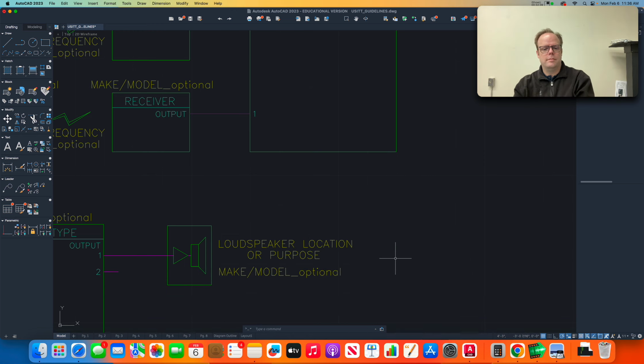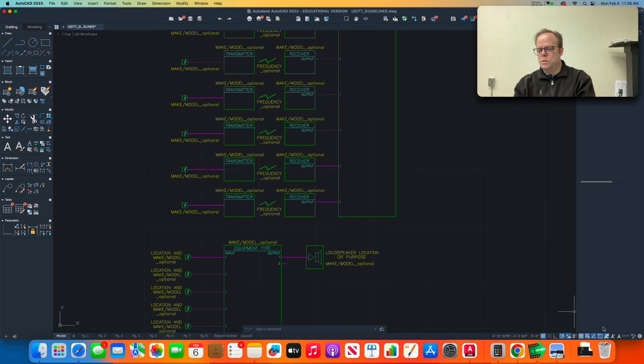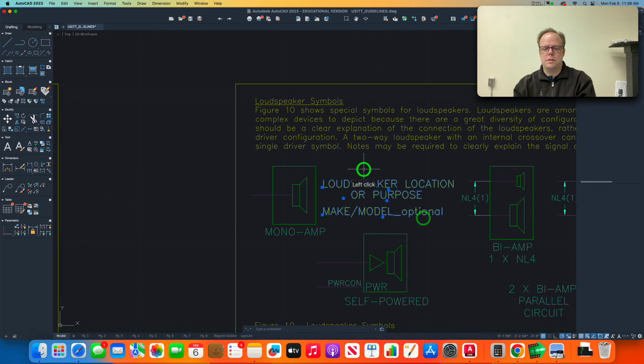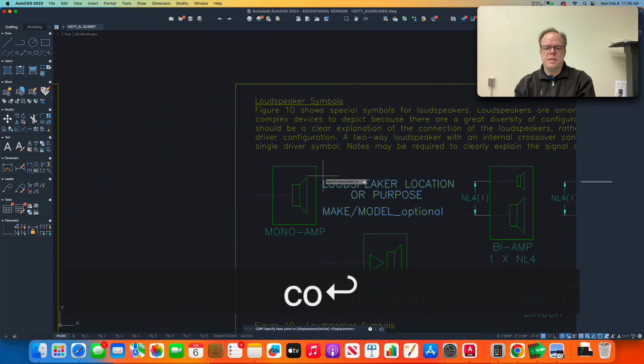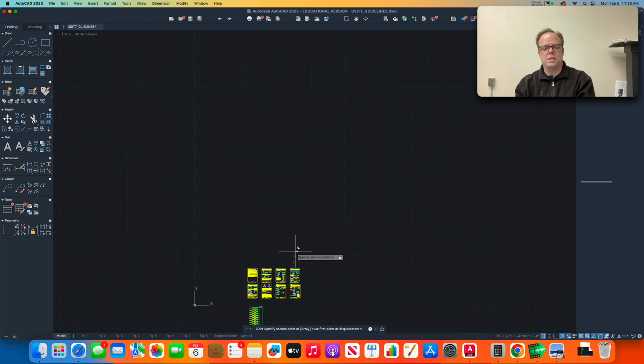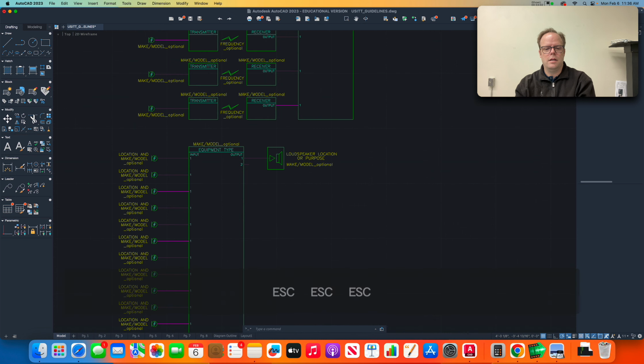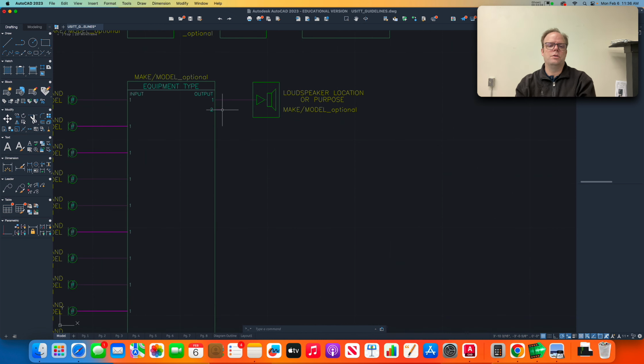How'd you find the midpoint? Using the object snap, so if you have midpoint turned on, I'll show you. If you have this selected, you say copy. It's base point, you just hover over the middle thing, and you see that triangle, that's the midpoint. It locks your cursor to that. And then you click, and then you can move, and you can do the same thing on the other end. I thought you were clicking the midpoint with text. No.